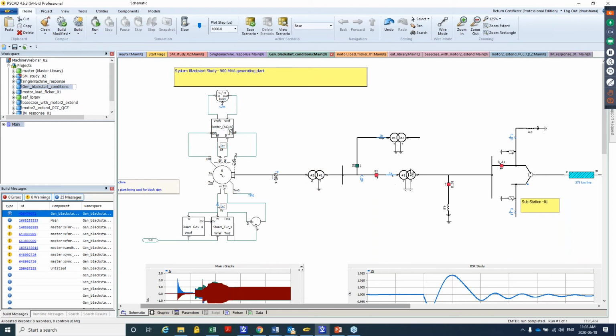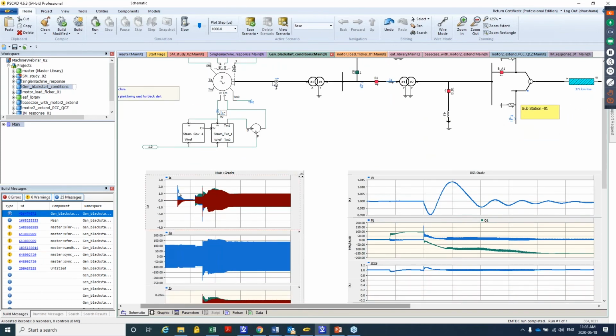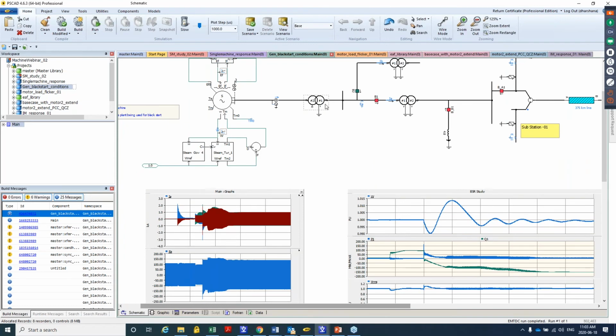can I energize my transformers without causing problems? So here I energize the transformer, and in this particular scenario, what I would look at is, would the voltage drops due to inrush current be too much to trip my undervoltage protection?